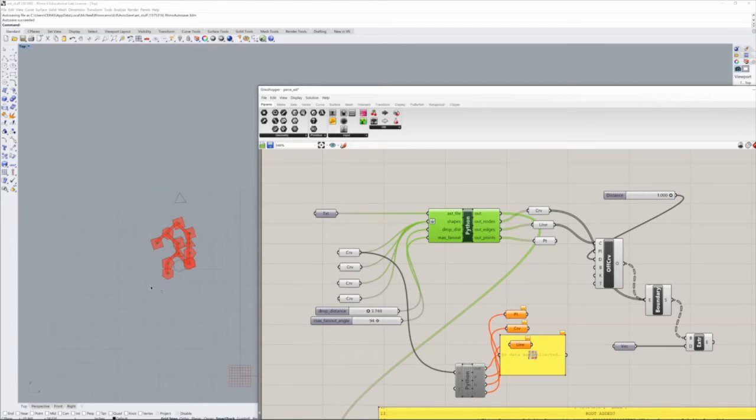And note that every time I change one of these inputs, the entire tree is regenerated, so all of the types change, so they don't necessarily have the same shape every time. And that's because these curves are being randomly selected to map to the node types. I can also mess with the offsets to determine how thick or fine the edges are between the nodes. And if I wanted to, I could also change this vector that defines how high it's extruded. I think I've got it set to about 1/2 inch or so.